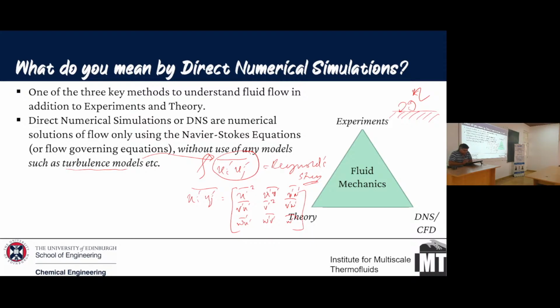Okay, so there is actually a story. There is something called the Reynolds stress model as well within the RANS system of equations. And some of these older RSM models used to have about 9 or 12 empirical constants, C1 to C12 or something like that. And the joke is that you can fit an elephant in it. No one knows what number to use there. So that is the problem with these turbulence models, that they're very empirical. Nowadays we probably have some idea about how best to use them, but again, it's a lot of trial and error.